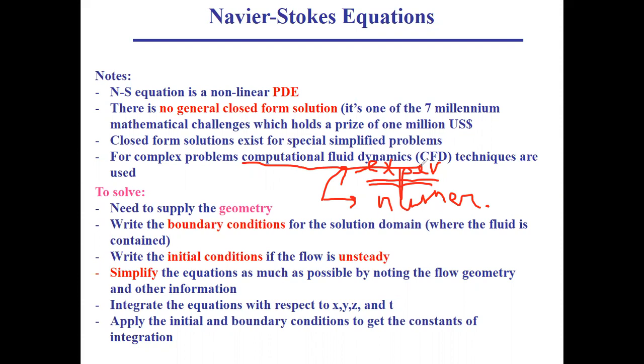So it's very important to determine the boundary conditions of the problem, and these will be inputs to your CFD software. So you should input them to your software, and it will perform the numerical calculations to give you the corresponding outputs. Now, if we have unsteady flows, we should also add initial conditions. So at t equals 0, we should specify what the conditions were, because this will affect the transient behavior of your solution.